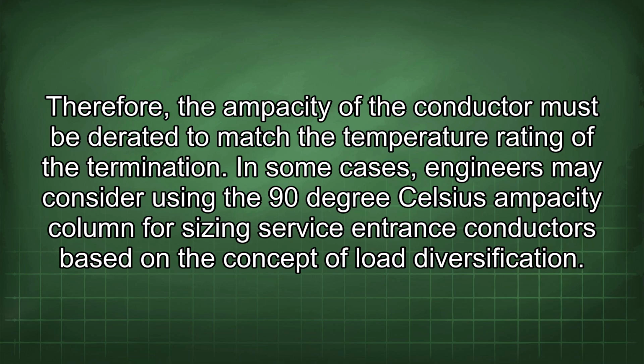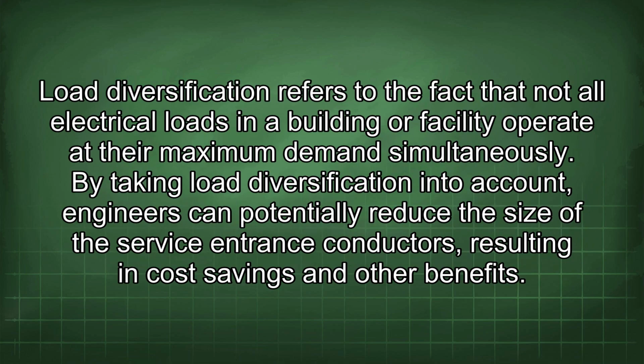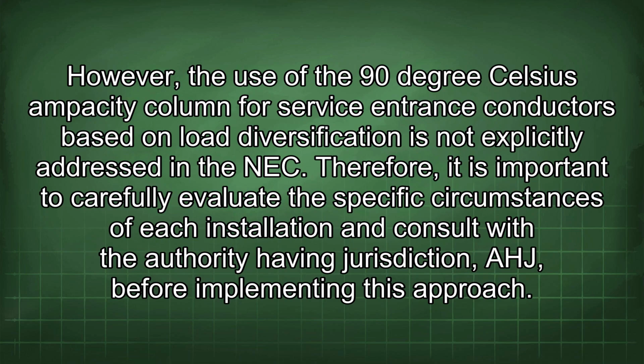In some cases, engineers may consider using the 90°C ampacity column for sizing service entrance conductors based on the concept of load diversification. Load diversification refers to the fact that not all electrical loads in a building or facility operate at their maximum demand simultaneously. By taking load diversification into account, engineers can potentially reduce the size of the service entrance conductors, resulting in cost savings and other benefits. However, the use of the 90°C ampacity column for service entrance conductors based on load diversification is not explicitly addressed in the NEC.